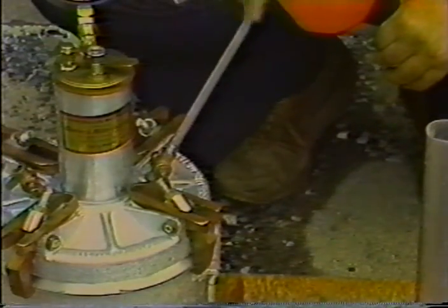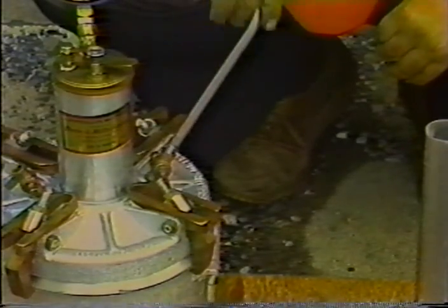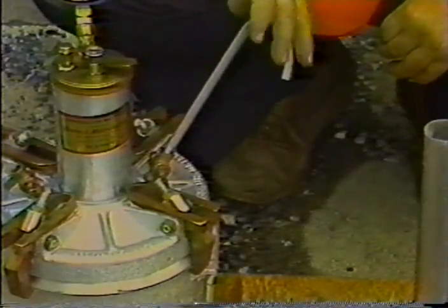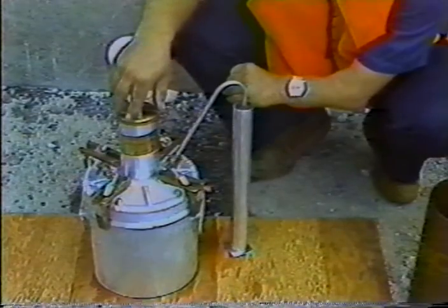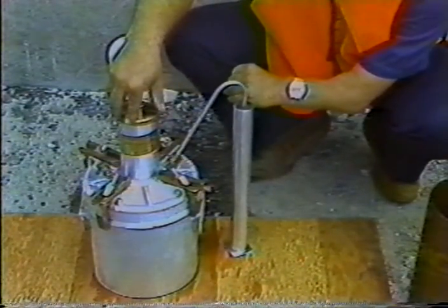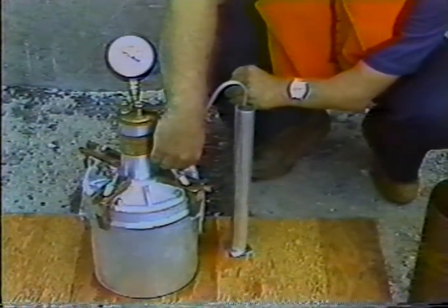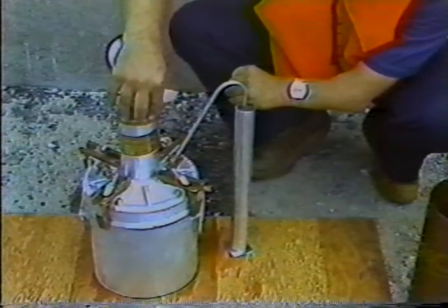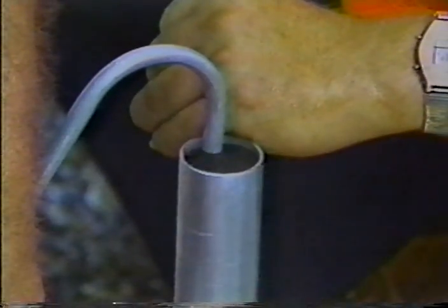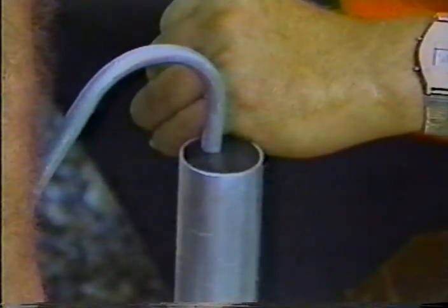If 2 or more tests show a consistent variation from 0%, change the initial pressure line to compensate for it, and use this new initial pressure line on subsequent tests. Then screw the curved tube into the outer end of the petcock. Fill the calibrating vessel with water from the base by pressing on the thumb lever and controlling the flow with the petcock lever. Usually this vessel holds 5% of the volume of the base.